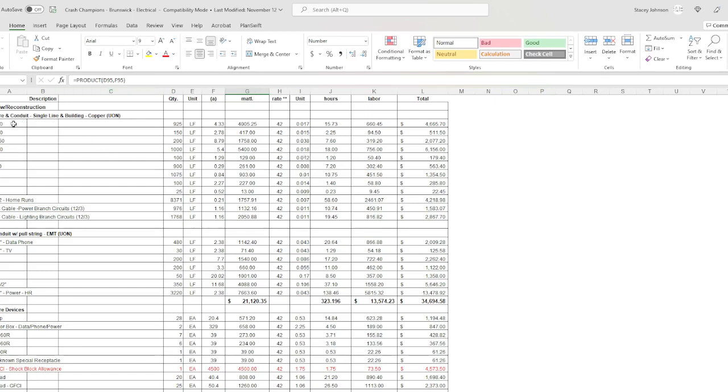The way we break it down, we have a section for our wire and our conduit, so all of the wire, even including for the single line, and then MC cable. Most of the branch circuitry can be run with MC cable, where all of the home runs, of course, have to be number 12. Or if it's a particular type of mechanical equipment, it's going to tell you that you need 3 number 10s and a number 6, or vice versa, and you'll know from that.